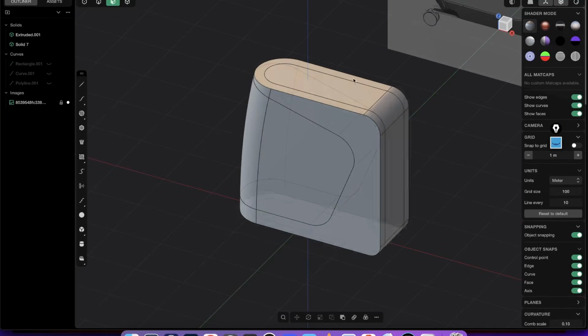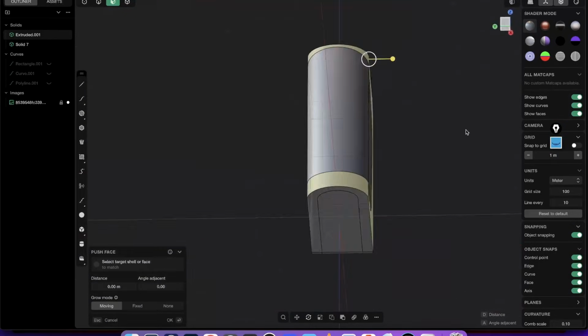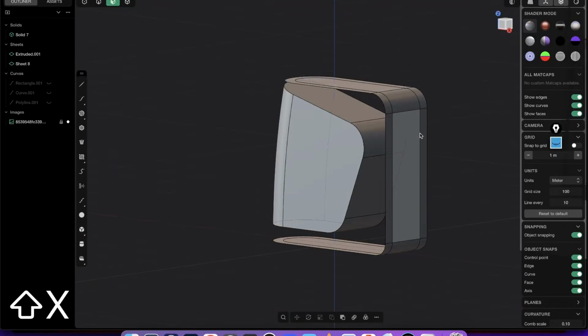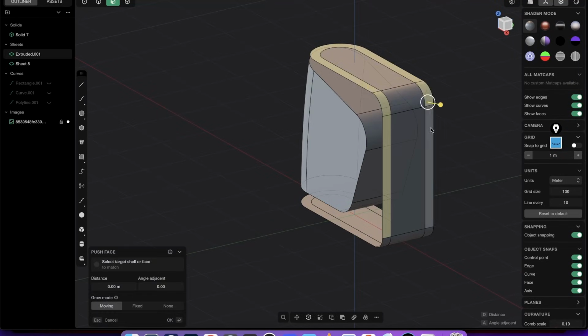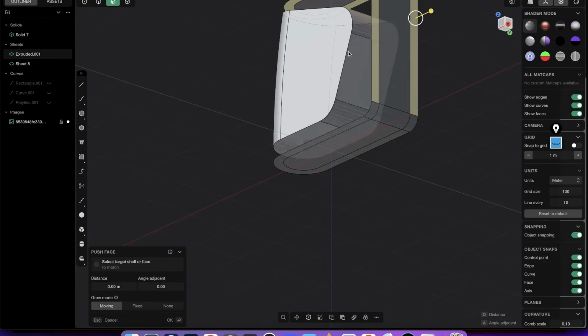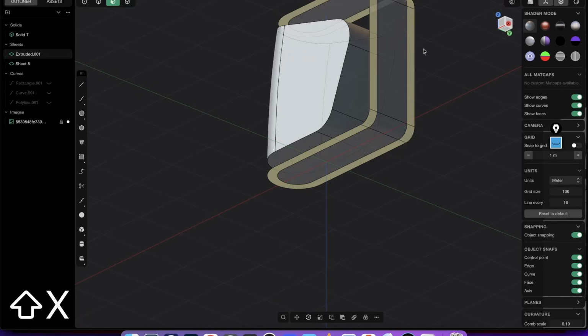So you can press Alt Shift click and it will select this whole loop here, and you can Shift X delete that. And here it's unfortunately not working. So we just have to, with Shift click one by one in face mode obviously, select all of those sheets and also again Shift X to delete them.